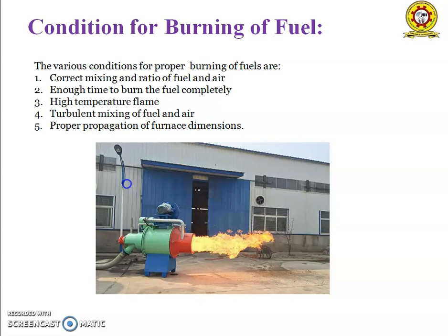It should deliver coal and air to the furnace in the right proportion and should maintain stable ignition of the coal-air mixture and control of flame shape and travel in the furnace.